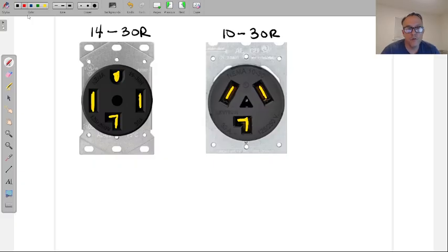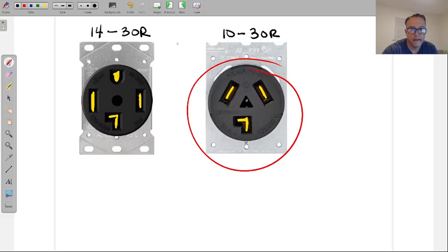But when you get into ordering from a supply house, which eventually you'll be in that arena, ordering outlets from supply houses, you give them the NEMA number. You don't tell them, I need a receptacle that's 120, because there's too many. If you see the NEMA catalog, the categories, it's a bunch of them. So we skip all that and I just say, I need 5 10-30Rs. That's it.